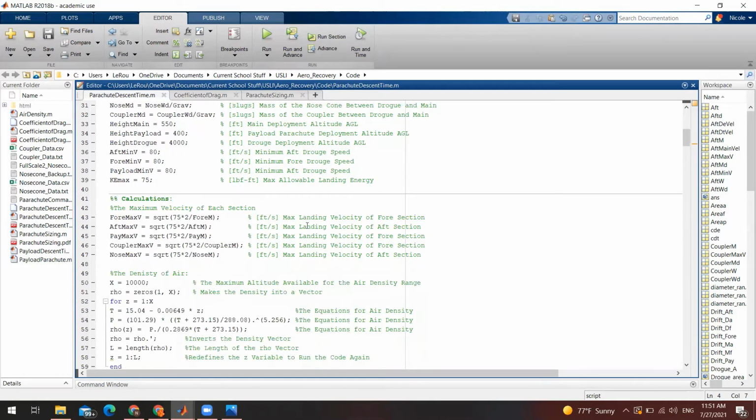So now down here, this is the altitude that we set our main deployment to happen at. This is something that we set in our altimeters. So we used a delay switch, since the altimeters that we were using were RRC3s, and you can only set per 100 feet, but we ended up needing that 50 feet to stay within our requirements. And so we had a little delay switch in there.